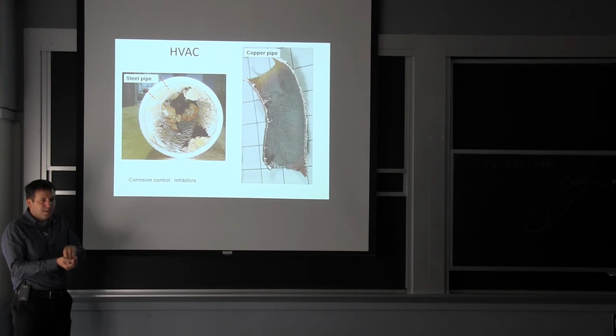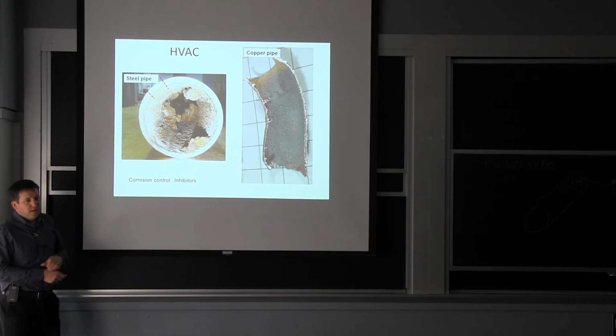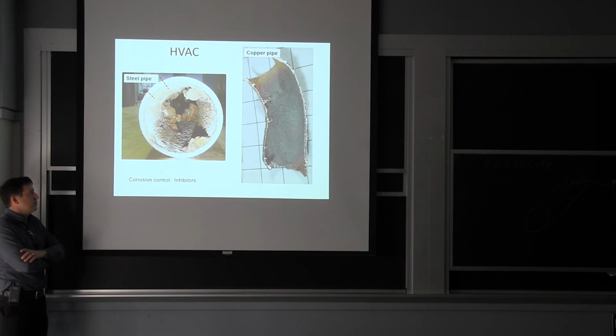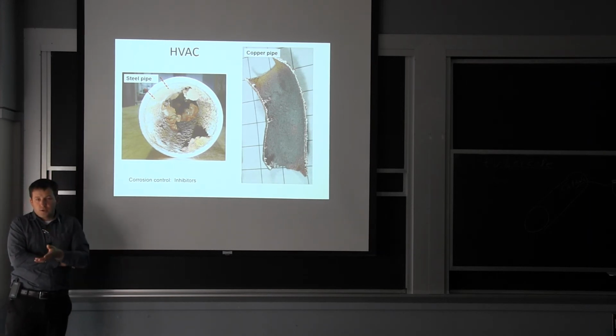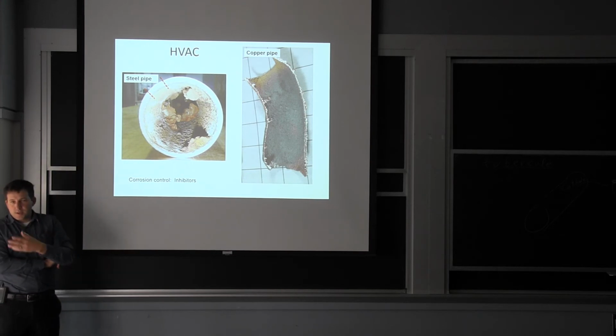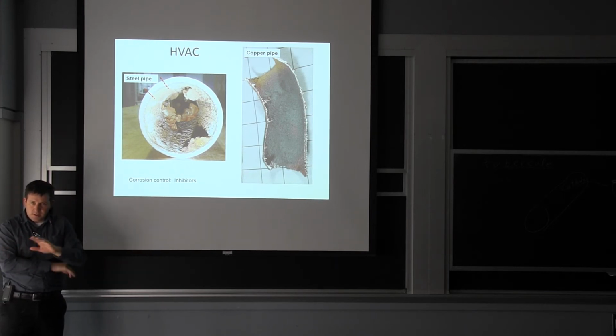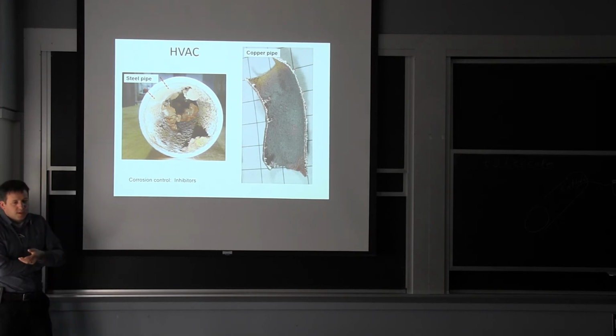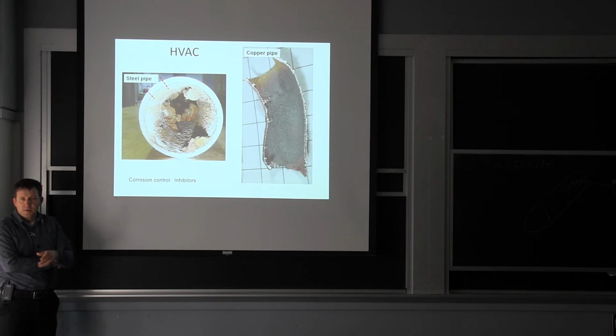You've already encapsulated your reaction, it will continue. So it's a big issue with plumbing systems where you think you have it right, somebody comes with an initial load of water and inhibitors, it really comes with a truck, they control the concentration and everything, and then the system starts getting used, and if you don't make up for your loss of inhibitor over time, eventually you're faced with a situation where you pretty much have to replace the piping, unfortunately.